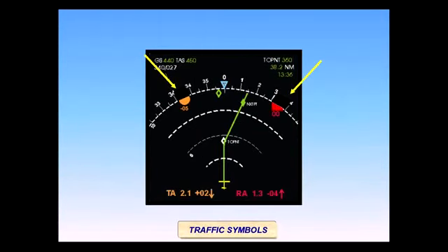Symbols will appear on the correct azimuth at the extreme limits of the display when they cannot be displayed because of the range scale selected. Data tags are color-coded the same as the complete symbol to indicate the level of threat. If symbols cannot be shown in the arc mode, or because TCAS is temporarily unable to track the contact, the data tag information will be displayed at the bottom of the screen, as shown here. This situation may occur if the antenna is momentarily shielded, or due to a partial system fault. Resolution advisory commands remain valid regardless of the nav display presentation.